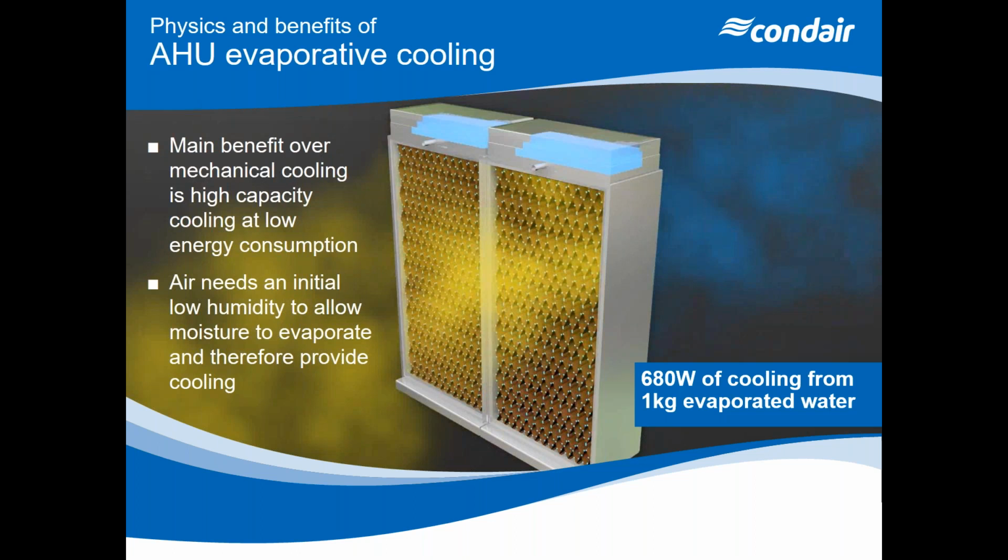So the huge benefit here is the low energy consumption because we're just relying on physics. We're just evaporating water into the air, sucking heat energy out of the air and utilizing that cooling. So we're not using any mechanical equipment here. We're not using a compressor. We're not using an oil management system. We're not using all of these things that would traditionally go into a direct expansion refrigeration system. We're not using a chiller or anything like that. All we're doing is evaporating water into the airflow.